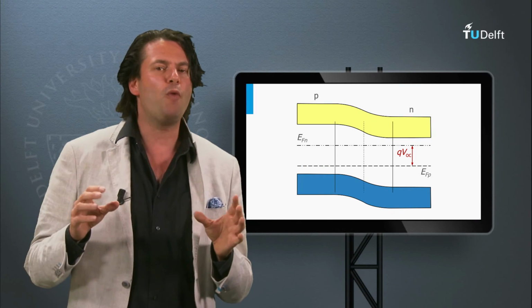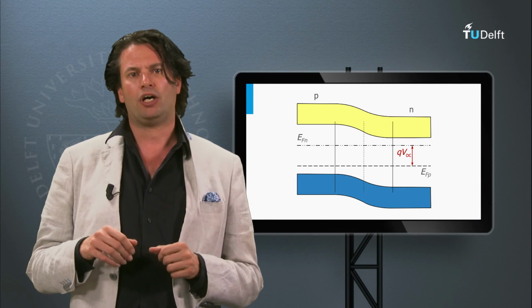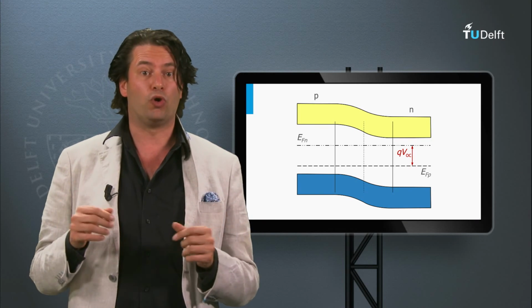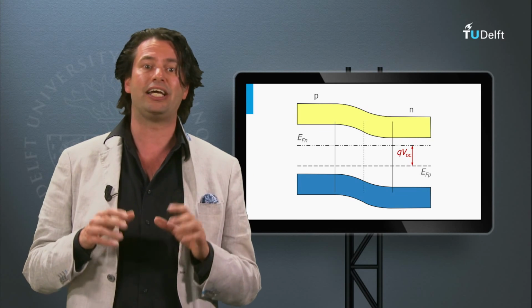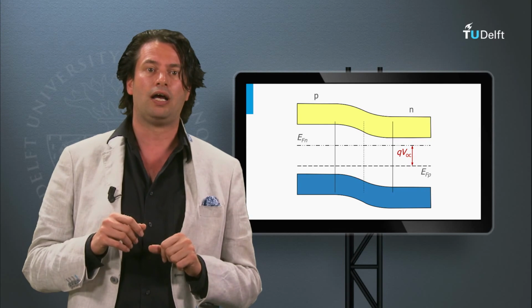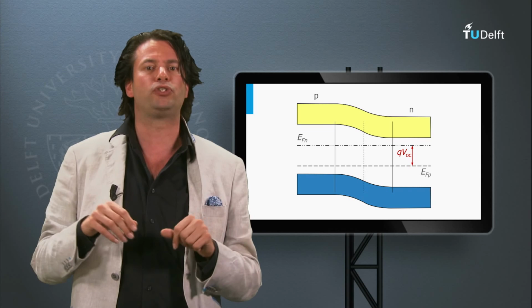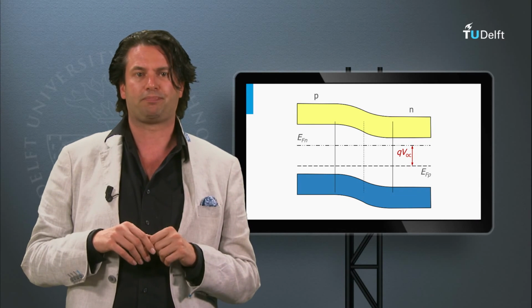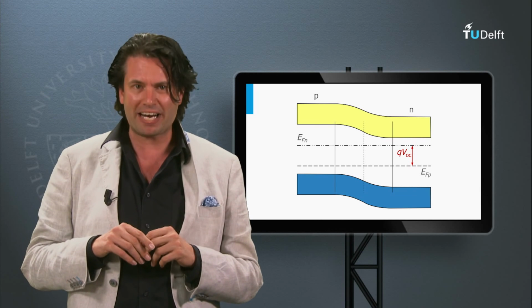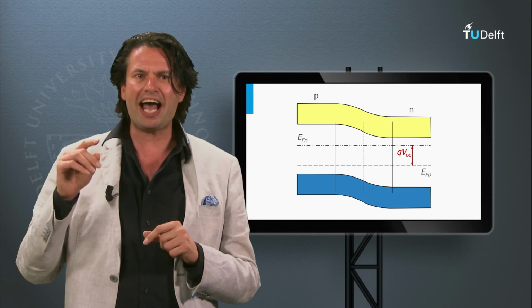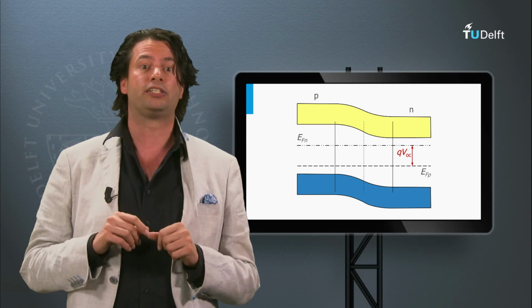Summarized, the open circuit voltage is limited by the dominant recombination mechanism. The dominance of radiative, Auger or Shockley-Read-Hall recombination depends on the type of semiconductor materials integrated into the solar cell and the illumination condition. In the coming weeks, I will give various examples of various PV technologies. In the next block, I will discuss the second design rule, spectral utilization. We will answer the question of how much current density we can generate with a certain semiconductor material.